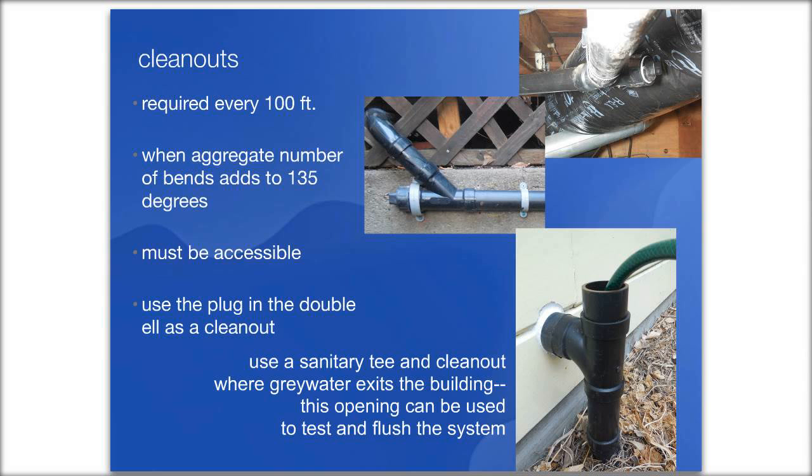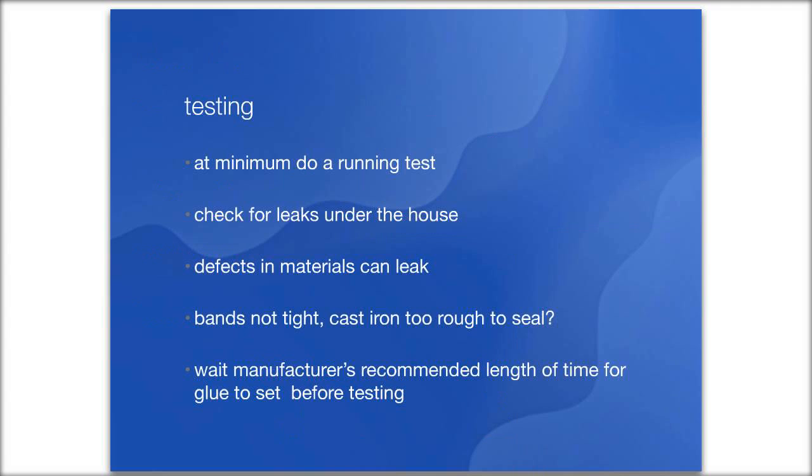And then if I want to, rather than going inside and turning on the water to test my system or see how it's all running, I can just put a hose into it outside. Or later on, if I think maybe there's been some accumulation of slime or hair or whatever, I can use a hose to blast out the system. So I think it's really nice to use that T when you're coming out of the wall before you drop down into the ground.